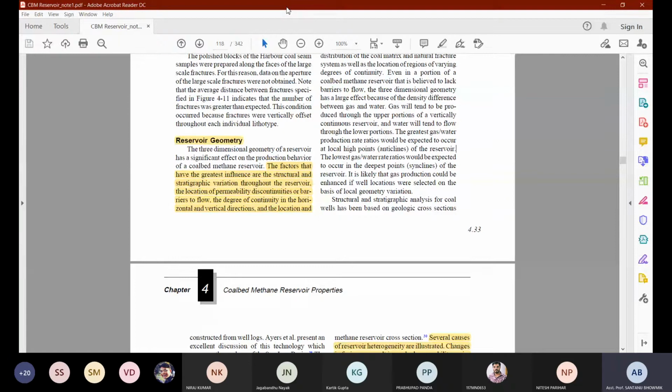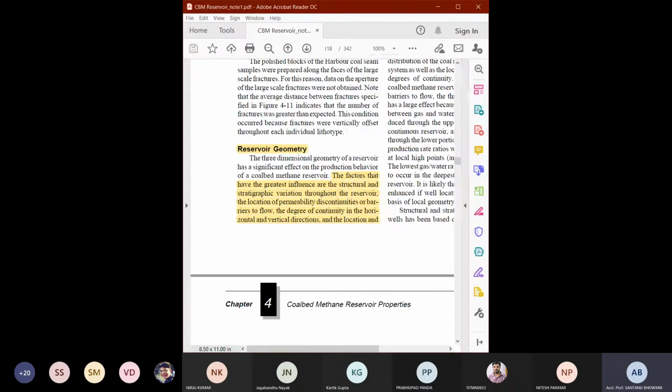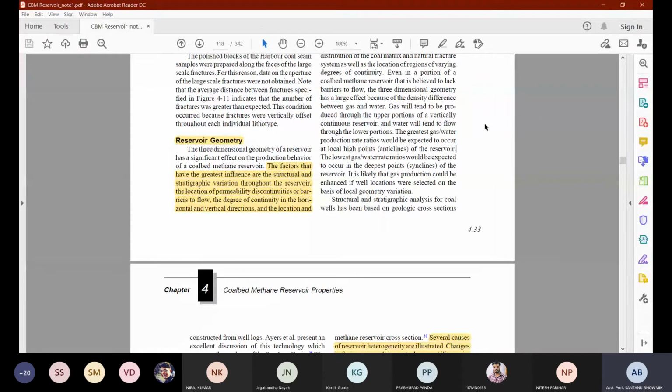In the second case, the stratigraphy. The stratigraphy means different types of rocks. Suppose you are observing the borehole log section, you will be able to know the depth and the thickness and accordingly the different rock types. When different rock types are present, you will be able to know whether the strata is soft or very hard, and based on this hardness and other parameters, the porosity and the permeability are obviously going to change. We will not get the same porosity and permeability in coal as we experience in shale or sandstone. For shale, you all know that depending on the bedding plane, shale is very weak along this bedding plane. You just put a tap with a hammer, and it will be fractured or separated.